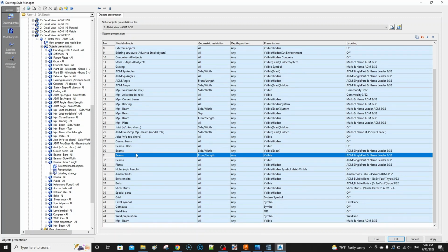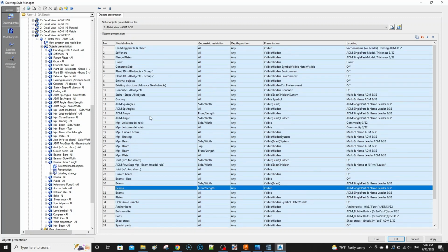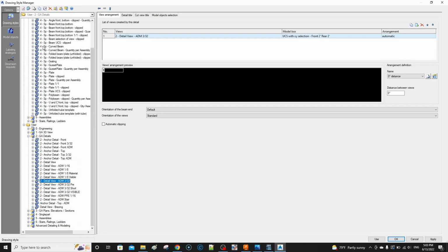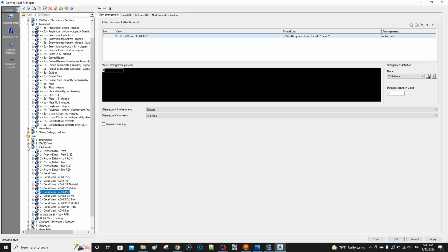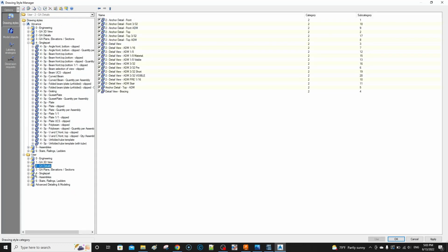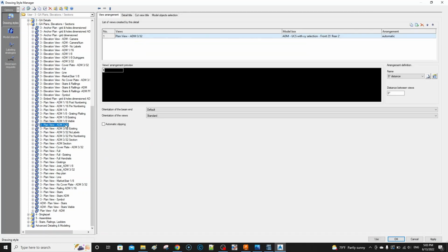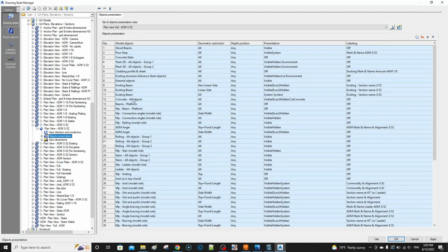So generally in plan views, this is a detail view. So I don't know what direction I'm looking in from, but in a plan view, let's see if I go to my plan view, right? So let's close this one for a second. And let's go to plans, and let's go to my plan view, which is 3/32. And there should be one labeled column in here, which there should be out of box, to be fair, and they don't give you one out of box.